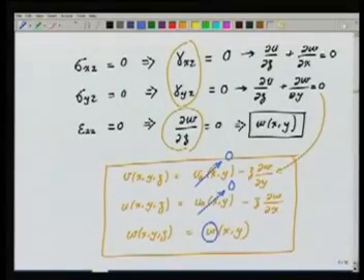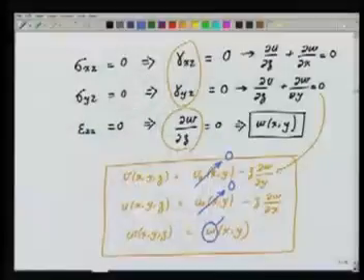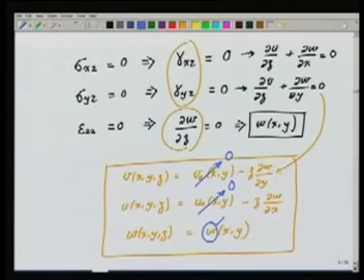So for this kind of loading, only w is non-zero, and u0 and v0 will be 0. If I had an in-plane loading along with this transverse loading, then yes, we would have u0, v0 also. If I had an anisotropic material, then also u0, v0 would be present. So remember, in this very special case, u0 and v0 become 0 functions.